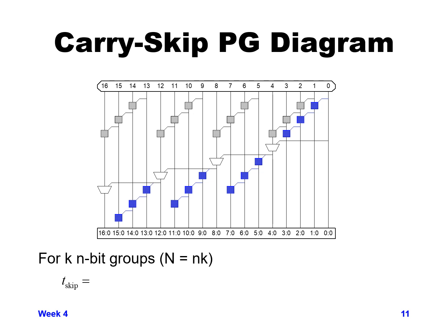You can see if we look at the graph, the longest path that we have, if we start at bits 0 or 1, is if we start at bit 1 and we go down and to the left, we have to go through 3 gray boxes to get our carry going through to our carry 4 sub 0.